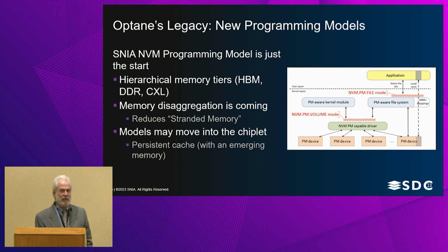So, for example, GPUs, which are widely used for artificial intelligence, use high bandwidth memory. This is a really tightly coupled to the processor memory. It has to be within 2 millimeters of the processor chip. And so it's always packaged inside the GPU's package. And it stacks. So once again, it uses this expensive technology that Samsung uses for the large DRAM DIMMs. DDR, of course, that's still going to be used for a number of years, and then CXL.